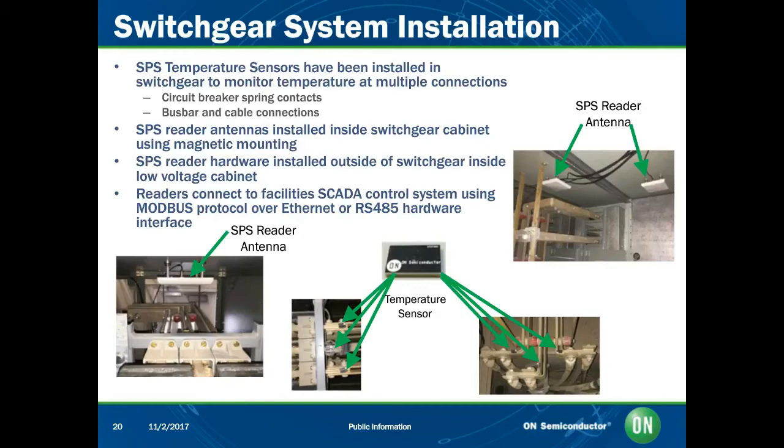So this is a closer look at how this system has actually been installed in some switchgear for a case study. One thing that I want to point out here is in the center of the slide, that black square is actually the sensor, so that's a slightly different form factor than what I showed previously. The reason for that is because this is being placed on metal surfaces, and we also needed to make it a smaller form factor, so we used a different design, but the technology is the same.